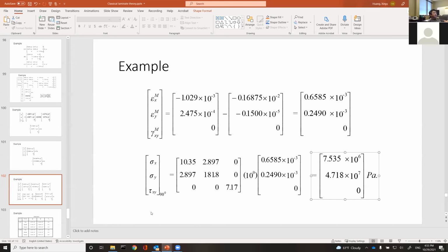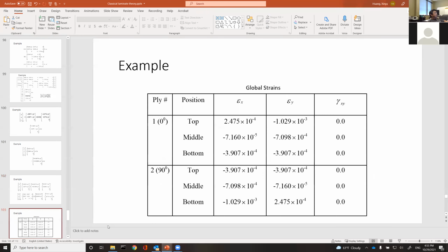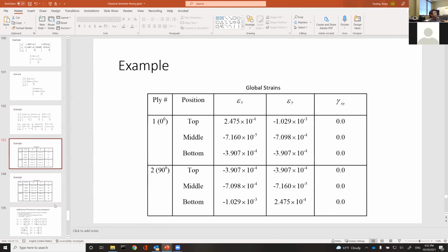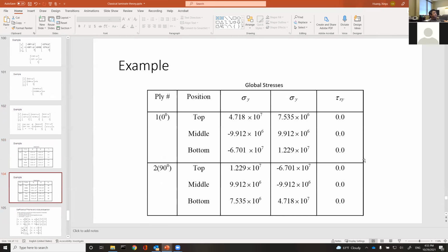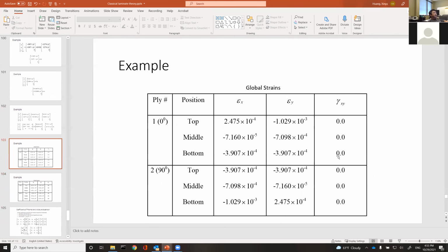This is a thermal mismatch stress. Remember, for the laminate, we didn't apply any external thermal load. We just let the layers fight. Due to the fact that these layers try to fight each other, they produce internal mechanical stress, which is calculated by this. And in summary, you can calculate for both layers what the mechanical stress and the mechanical strain are, like this. And this is only the thermal effect.